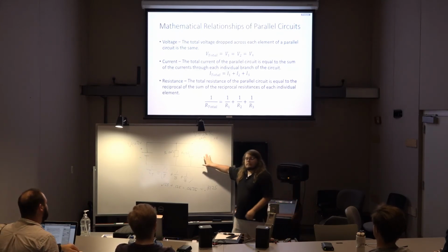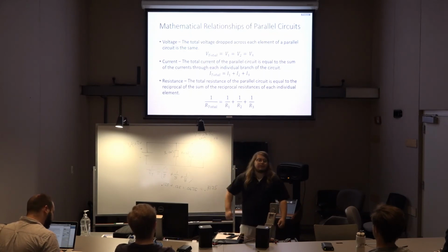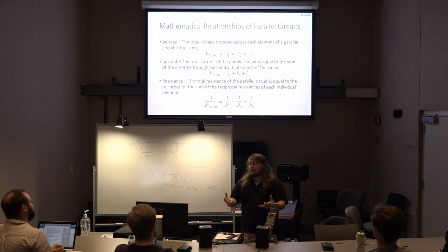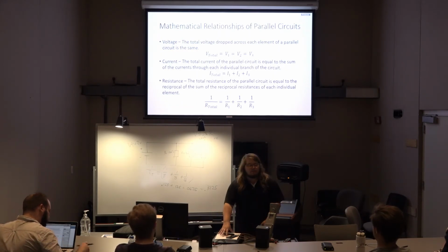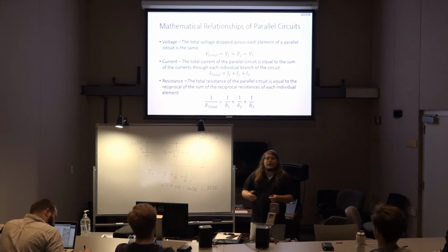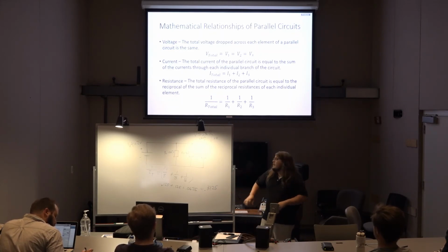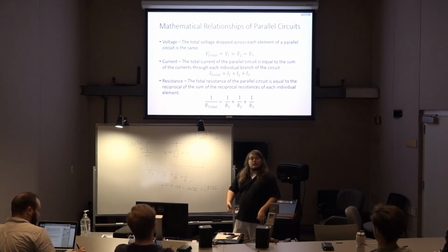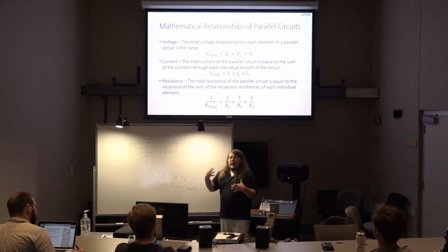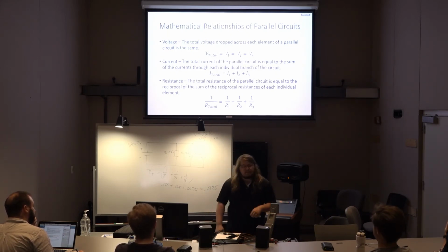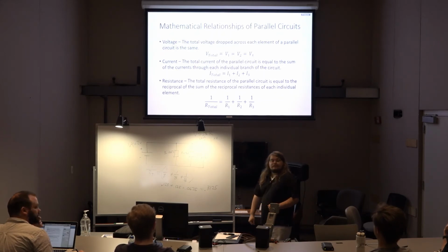Paralleling these speakers or resistors allowed us to increase the power. The cost is increased current draw. This power amp is a real physical item that has limits because of physics, so there's only so much current that we can ask from the power amp. But the way that we've arranged this circuit, we're drawing more current, we're getting more power. So there's some potential upsides to that, but we can only do it so much.